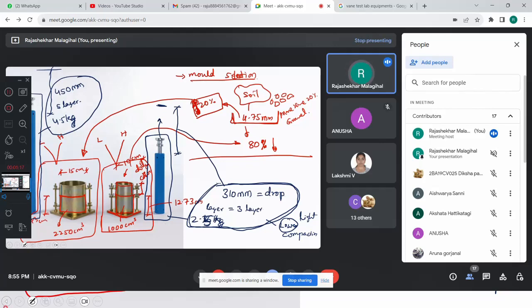For CBR, sir. Modified compaction, sir. That is the CBR test, no, that is a different test. Modified also uses it, sir. Modified compaction means heavy compaction. Yes, sir. For heavy compaction you want to give 56 blows? Yes, sir. No. Then only 3 layers are used, sir. Where 3 layers are used, there you will give 25 blows.